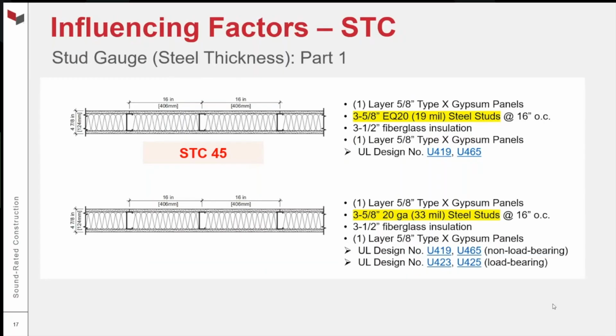All right, let's talk about stud gauge. So now we're just looking at steel studs. The wall on top is the same wall that we were looking at before, STC 45. This is our EQ20 19 mil studs, 16 inches on center, non-load bearing 1 hour fire rated wall, STC 45. In the wall below, we're looking at the same construction, but we've swapped out those studs for a 20 gauge 33 mil stud. So this is a structural 20 gauge stud.